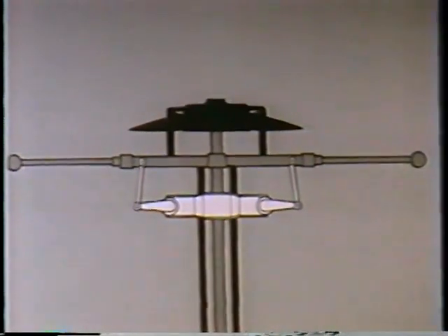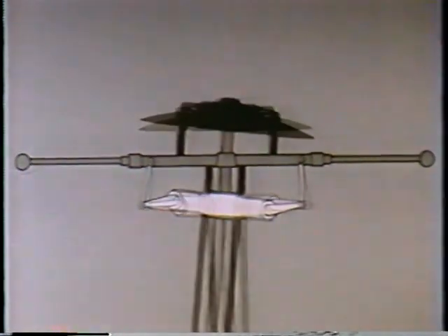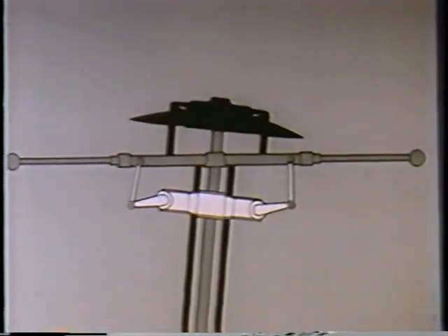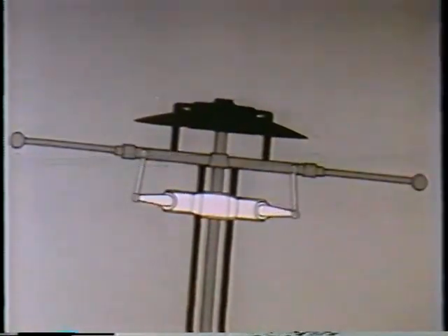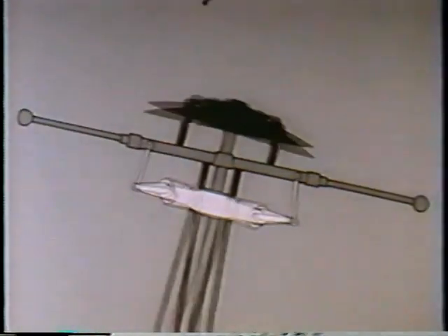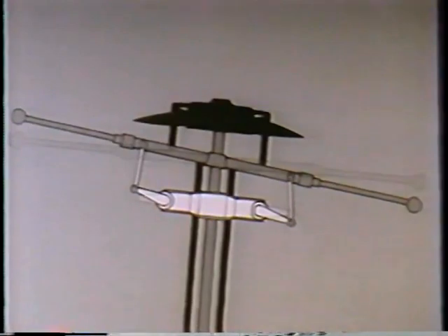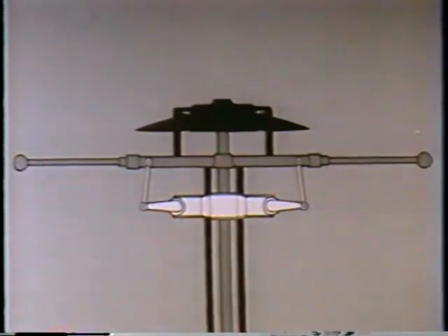The mast is tilted in directional flight. The damper assembly is tilted with it. Since the stabilizer bar tends to remain in its same plane of rotation, the dampers immediately exert pressure on the bar, causing it to realign itself with the mast in 3 to 5 seconds.